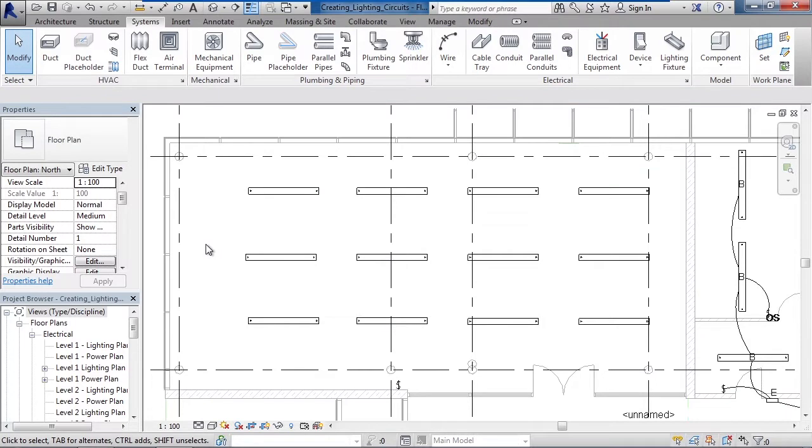Now, for the cosmetic lines or arcs that define the wiring, we have to actually draw wires. This is purely for a cosmetic view to show the electrician or the installer what your theory is of what light should be connected to what light in the order that you lay this out. However, the circuit, though, is already built.